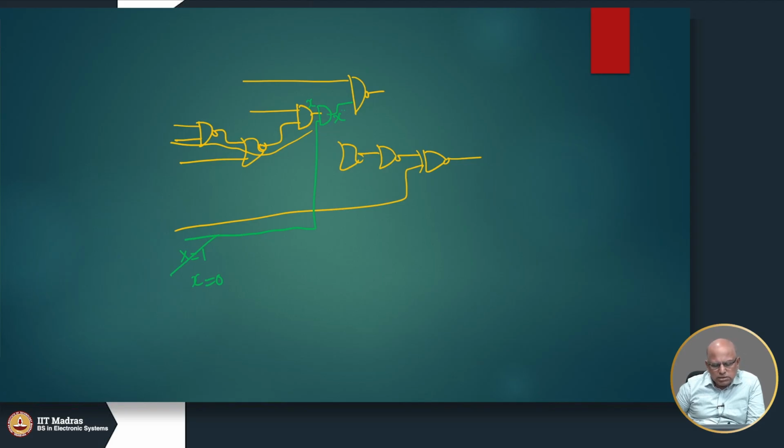So, they are just blindly looking at it as a gate level circuit. So, when PODEM tries to put a 0 here, if it follows this path, it is very easy, just put a 0 here and it will work.